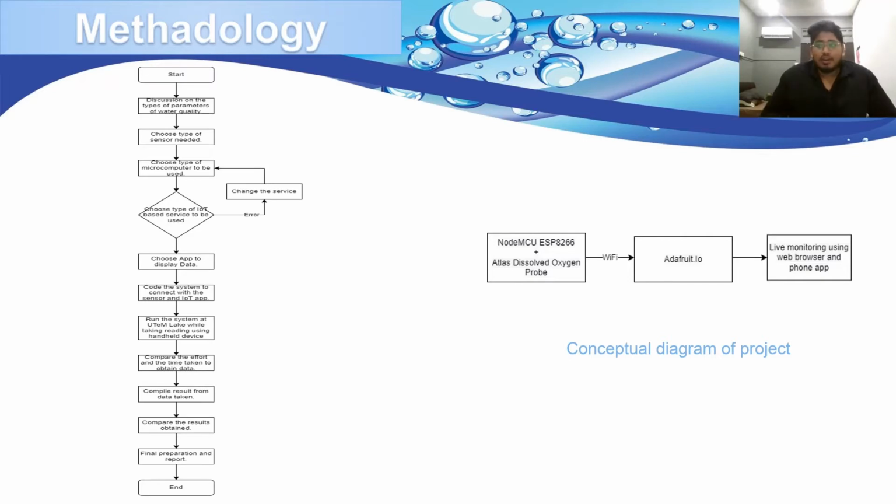And on my right over here, I have the conceptual diagram of my project, the basic concept of my project, where the Node MCU and the dissolved oxygen probe are wired together, which is then connected through Wi-Fi, which sends all the data received by the probe to Adafruit IO, where it compiles all the data and presents it in a presentable form in gauges and in graphs. And after that, live monitoring using a web browser and phone app.